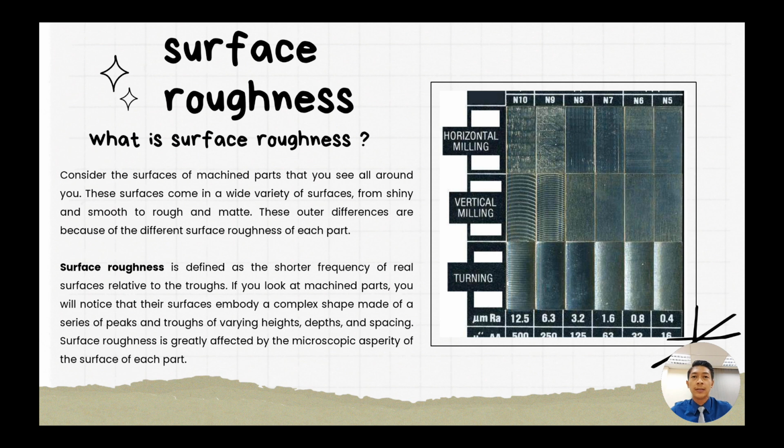However, in some instances, a smoother surface is required. A smoother finish can be desirable when designing a sliding part, as it will reduce the friction between parts and increase performance. It requires an additional slower machining step or a post-process finishing step such as polishing to achieve a smoother finish. Manufacturing costs increase as roughness reduces, so there can be a trade-off between surface roughness and cost for some parts.